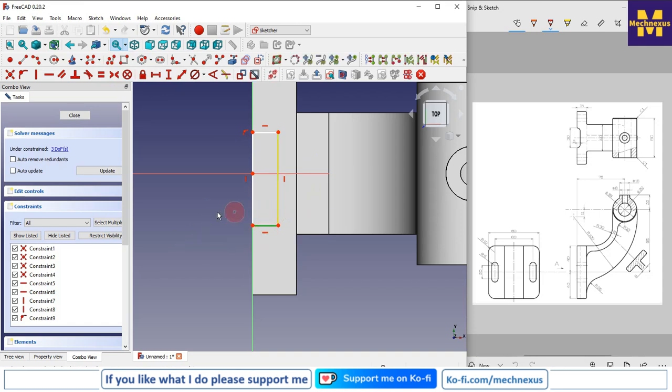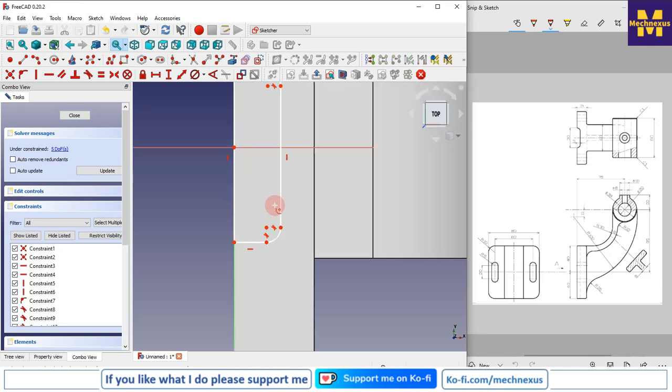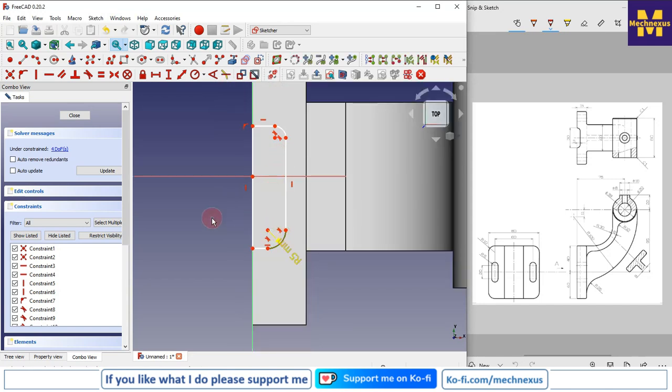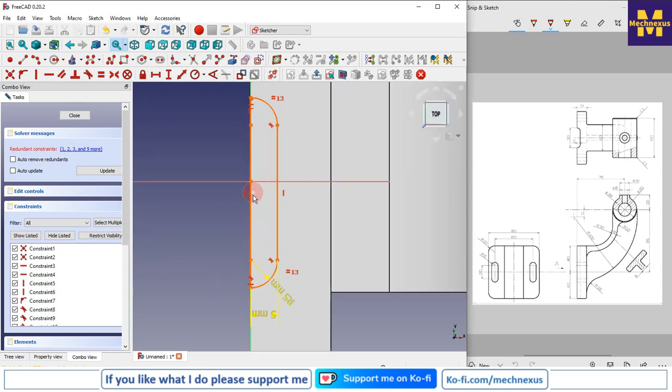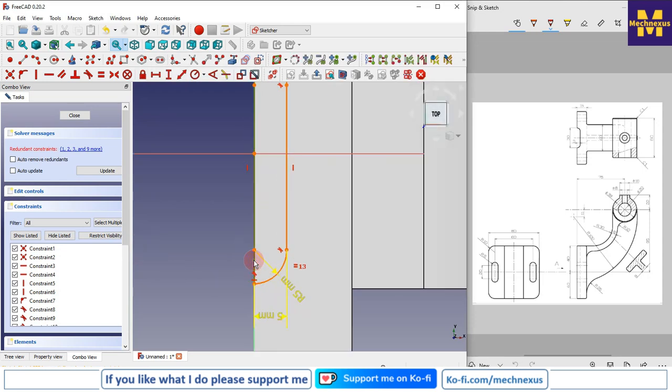and give the fillet to this and this, this and this, and I will give this radius as 5 mm. Similarly this one and this one, made it equal, and give the 5 mm. So here is a conflict, so it is better to delete this line.